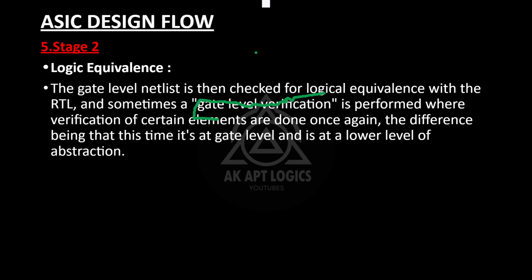So we will do all the design code firstly in behavioral. If the design using that behavioral model is okay, then we will convert that particular code into gate level modeling. Why? Because using behavioral we are going to specify only functionality, right?